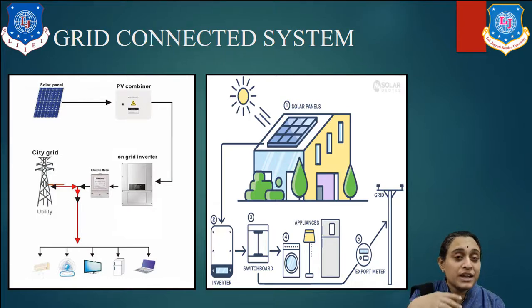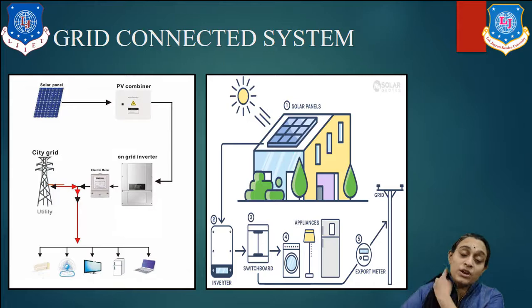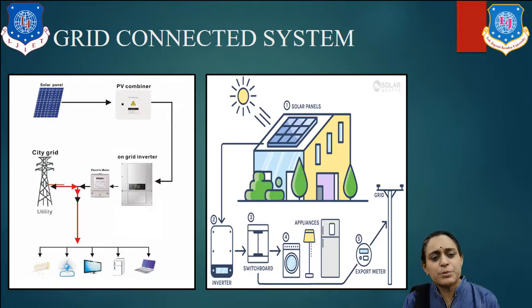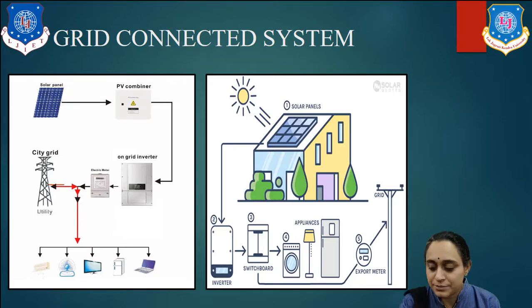It means on the roof top we put our solar cells and solar collectors, just a kind of grid connected system, as you see in this diagram. Nearly 20 kilowatt for housing colonies and 100 to 200 kilowatt for schools and factories. The system operates on the principle of feeding power into the grid when solar generation exceeds the local demand and taking energy from the grid when required. It has no storage of energy, but it needs components to regulate voltage, frequency and waveforms. So for household purposes, we are using the grid connected system.